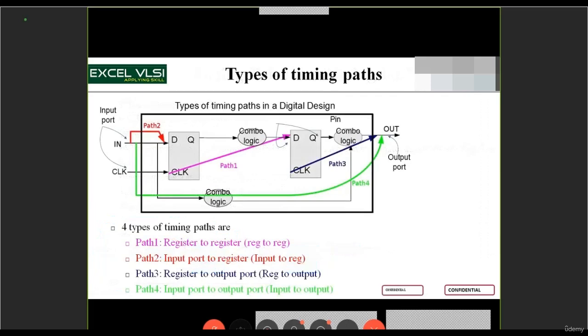You can see any circuit in the gate level netlist form that you get if you are an STA engineer. The complete circuit will be segregated only with the naming attributes of such kinds of paths. A circuit that starts with an input port and ends with a register will be one set of paths, and a circuit starting from a register and ending with a register will be another set of timing paths.